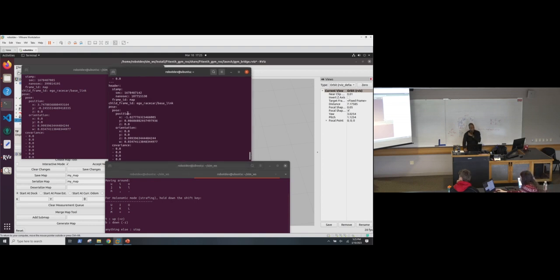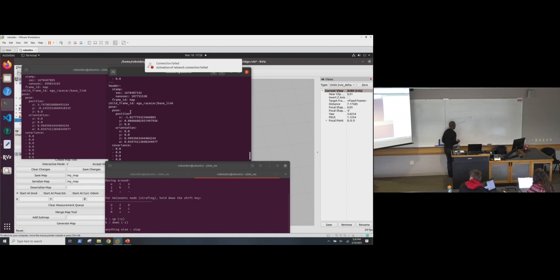So if I subscribe to this pose message, I can get its position out. So here's your robot. And again, it's broadcasting its odom information. But odom.pose will be its X, Y, Z, and then its roll, pitch, and yaw pretty much out of there.